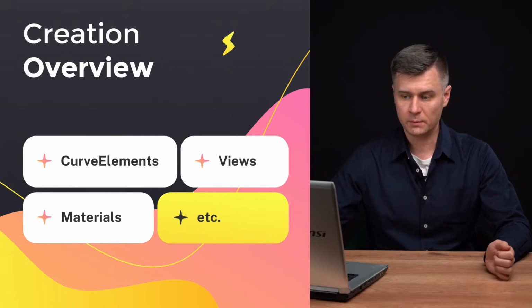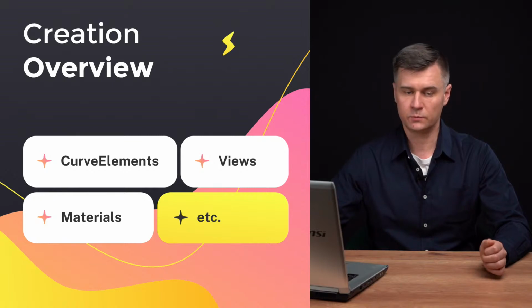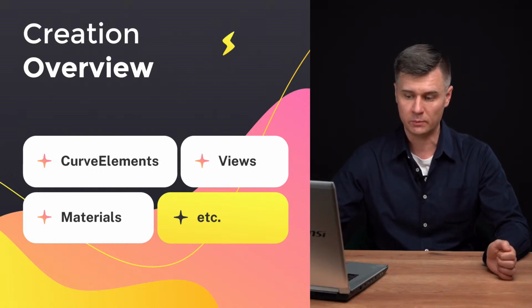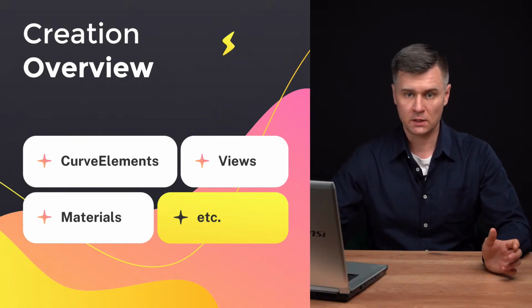It includes curve elements, which can contain line, arc, ellipse, spline, etc. It's possible to create custom parameters and their instances. It's possible to create connectors and materials, different views, 3D views, section views, levels, etc. It's possible to create direct shape, freeform elements, and etc. Different forms based on extrusion, revolution, sweep, blend, swept blend, etc. Boolean operations for two-form elements are also possible.